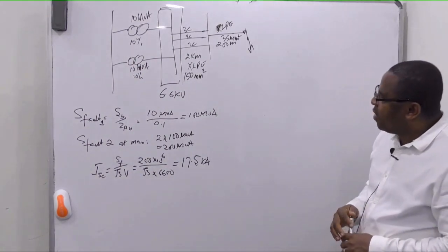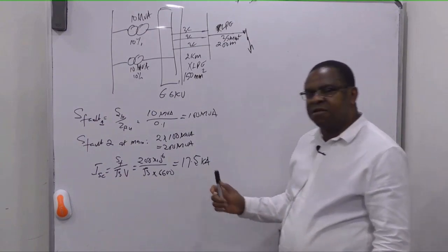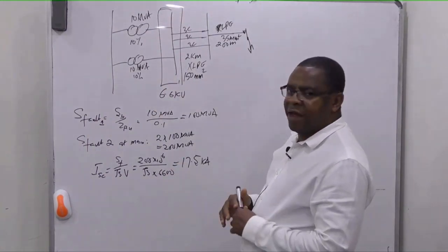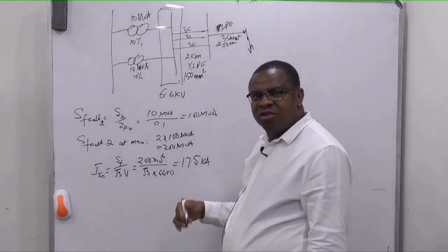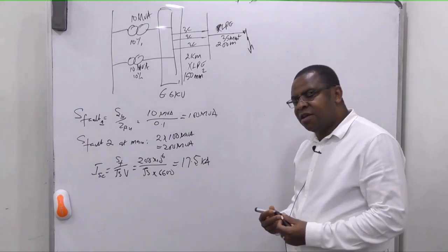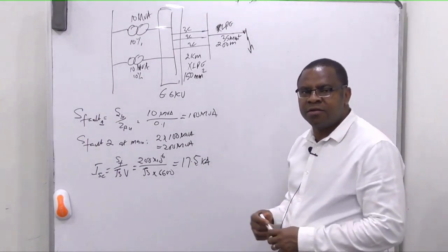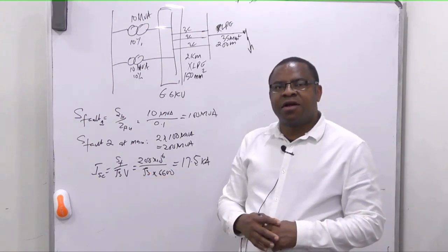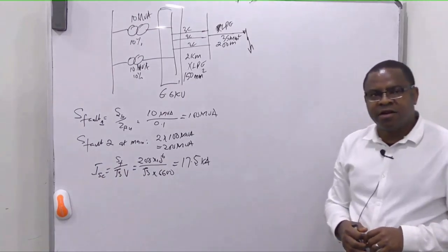All right, so this will be this. That means the circuit breaker size, I mean the switchgear in kA, will be something more than that. Maybe a 20 kA, 18 kA, or 25 kA board. Okay, so that's the first thing, to determine the main switchgear rating.